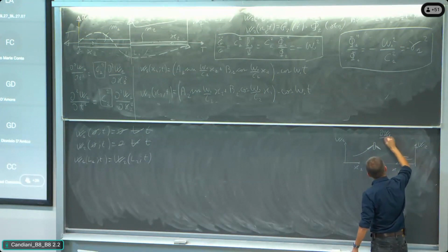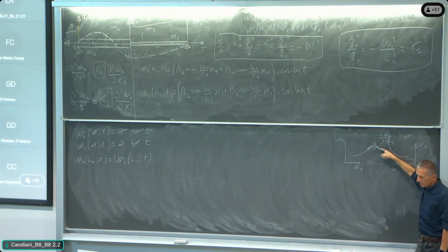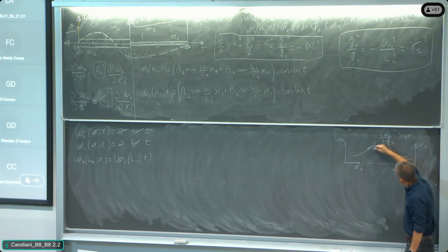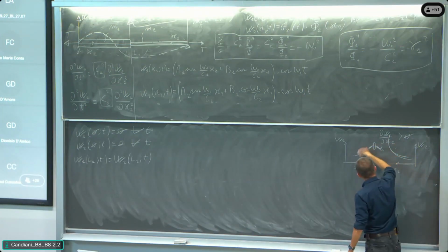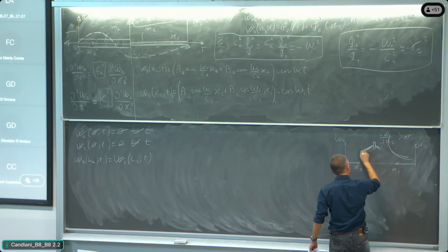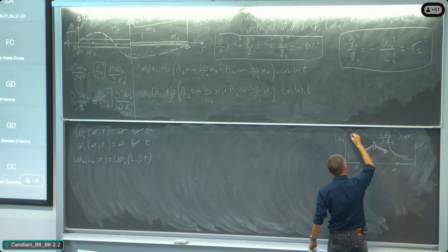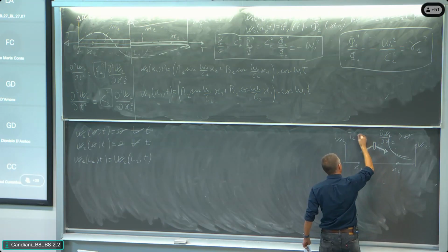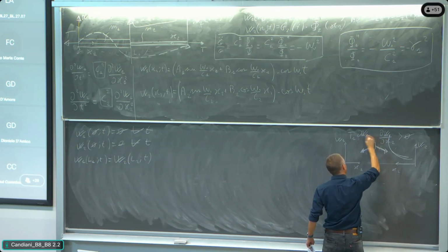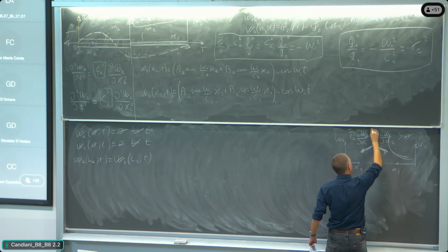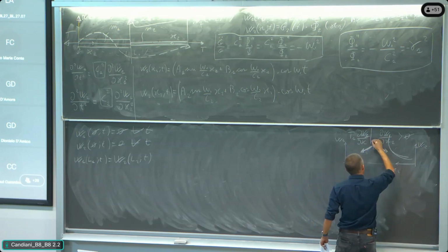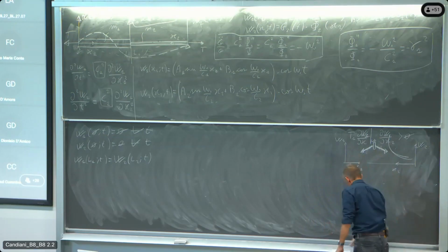The positive derivative, so d²w2/dx2 larger than 0, that I must use in order to write the generic condition, has this direction. And so if I have to write the boundary condition of the tension, this quantity here is tension T1 dw1/dx calculated at L1, all right?